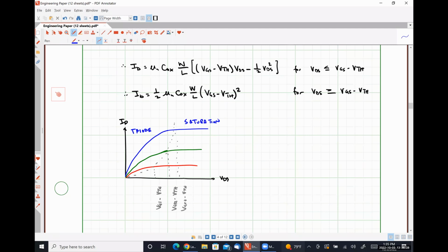So we are going to be talking about amplifiers. And the amplifiers that we are going to be talking about rely on our transistor's ability to turn a voltage at the input, so a voltage at the gate terminal, into a current flowing through the drain terminal, okay? And that relation is best described by what's called the transconductance of the device,